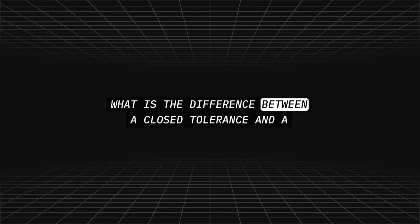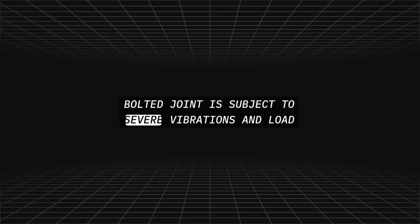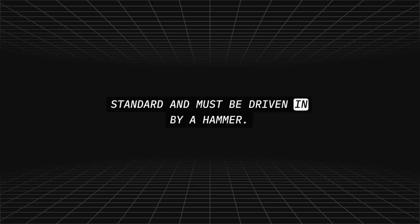What is the difference between a close tolerance and a regular AN bolt? Close tolerance bolts are used in applications where the bolted joint is subject to severe vibrations and load reversals. Also, close tolerance bolts are machined to more precise standards and must be driven in by a hammer.